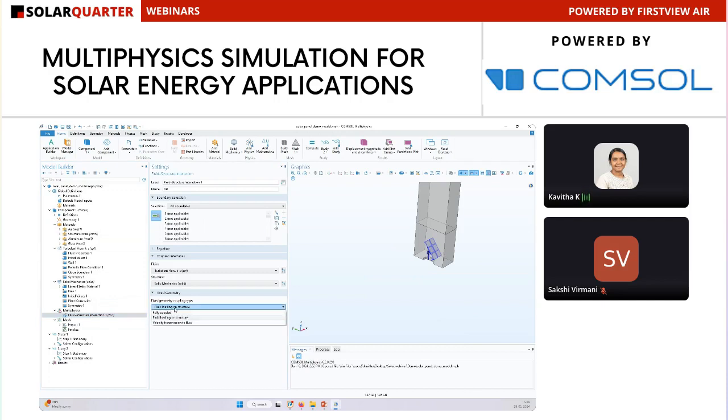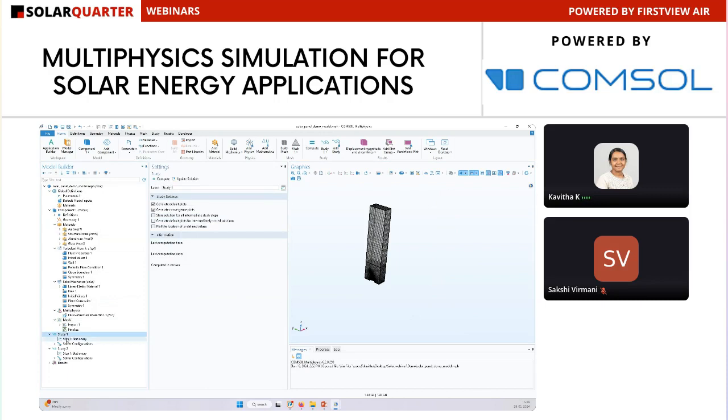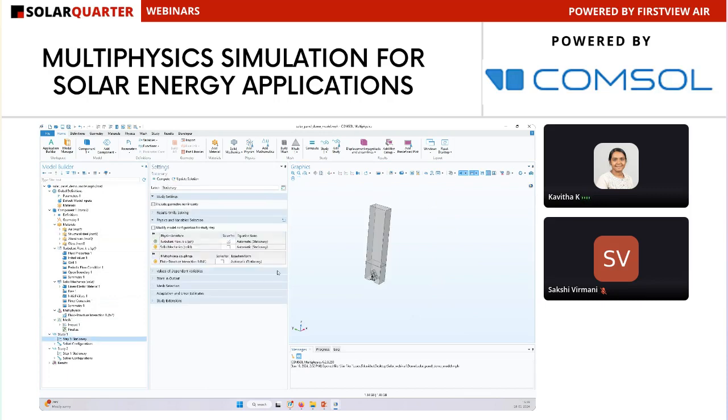But in case you want to have fully coupled, then you can also use fully coupled simulation. Already this is a mesh file. In case you have created the geometry, then you can use the physics-controlled mesh to mesh the geometry, or you can go for the user-controlled mesh where you want to specify more refining for your structure. Then you do the first study, which is the stationary study on the turbulent flow physics interface.